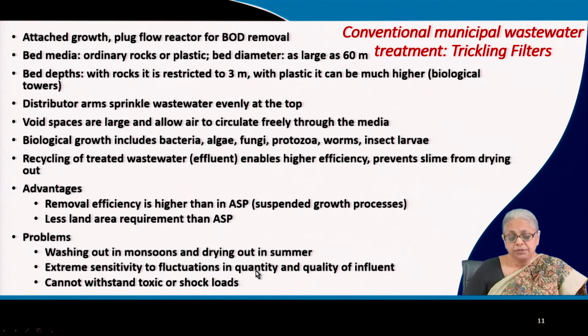Any fluctuations in the quantity and quality of the influent are also going to have a huge impact on the quality of the effluent. So any fluctuations in the input will be reflected directly in the output, and this is not the case with ASP. So this process has no ability to withstand toxic or shock loads.